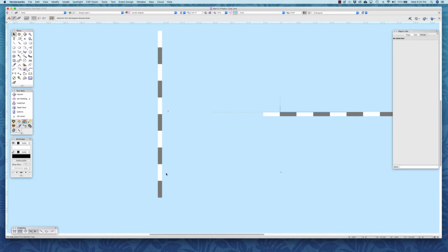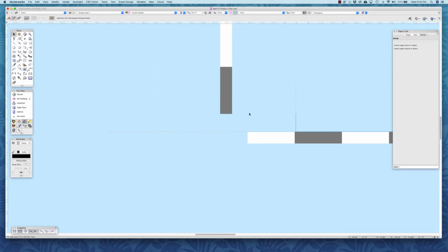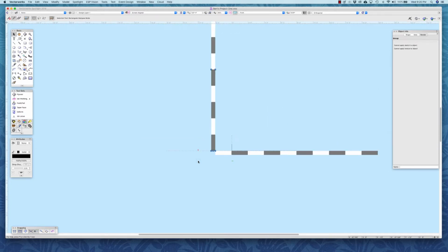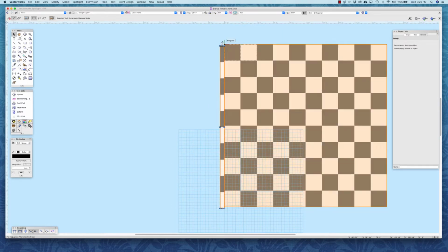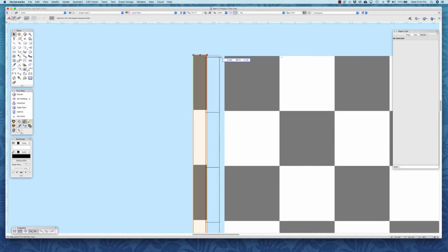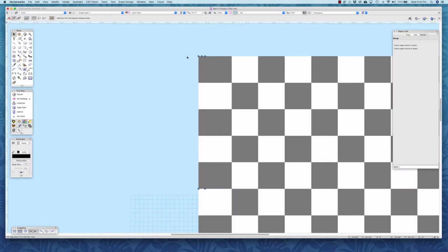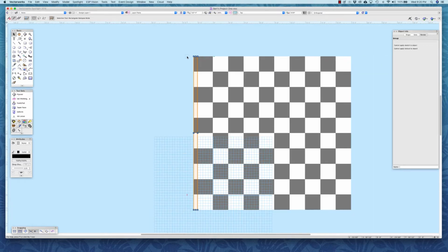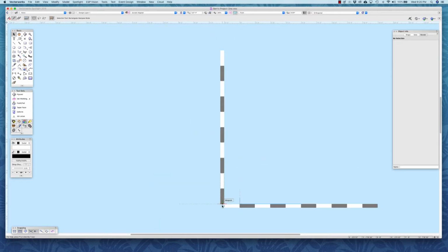Now align the wall to the floor, noting that the wall sits on top of the floor, not beside it. Switch to top view and make sure the wall is aligned in this view as well. Note that when you move an object in one view, only 2 of the 3 coordinates are affected. Moving the wall in the top view does not change its previous alignment in the front view.